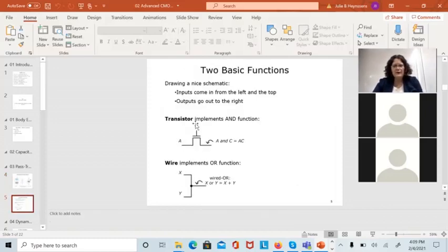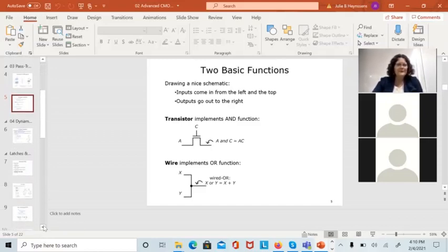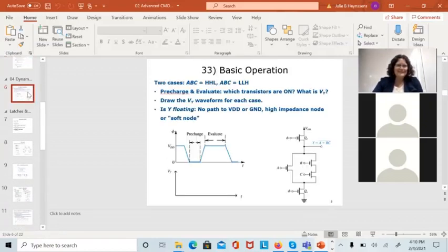Pass transistor, what's on the drain, what's on the source, ANDed together. That's AC, and this wired OR coming out. Because of the Shannon criteria, if you're given a pass transistor circuit, the function, and you just use these basic rules, the function you get out will not be in its reduced form. You may have to do a little bit of Boolean algebra reduction. It's the usual things, 3 rules nobody remembers. If you don't reduce it, I don't mark it off completely. I just take a few points off.